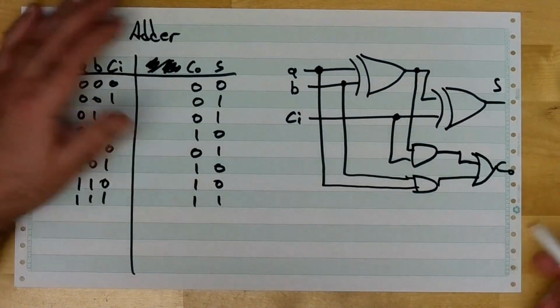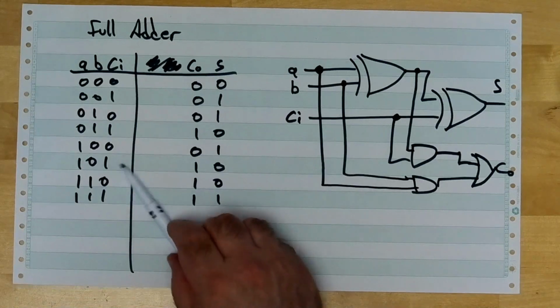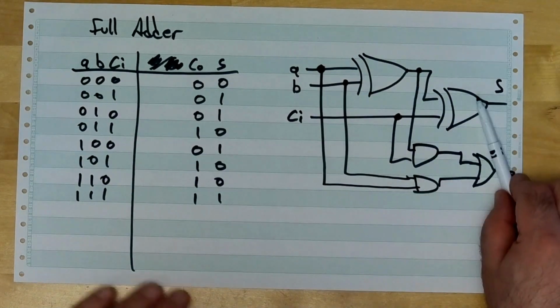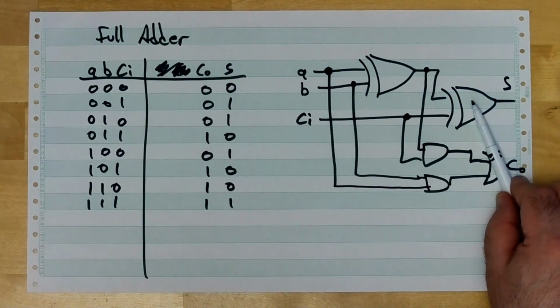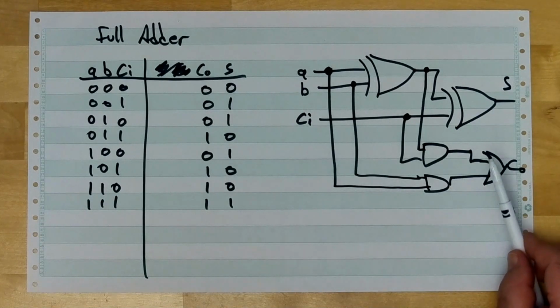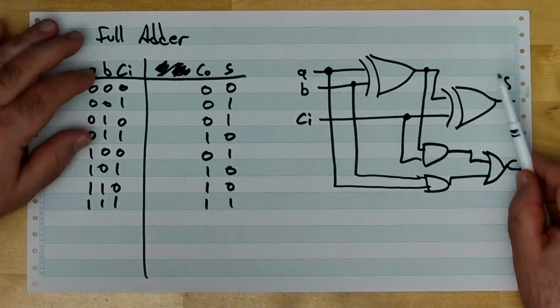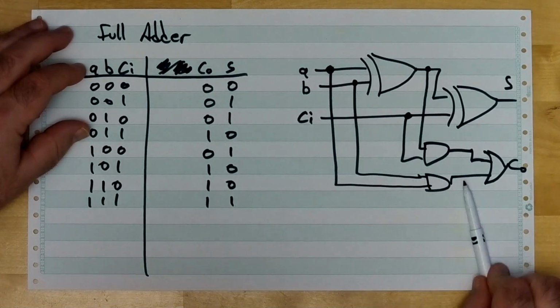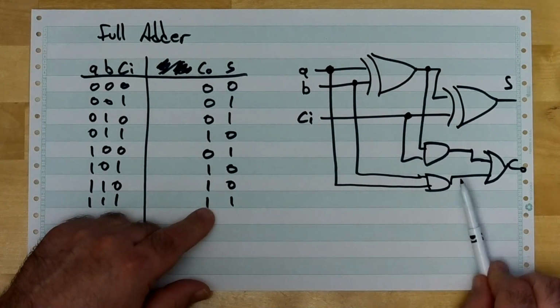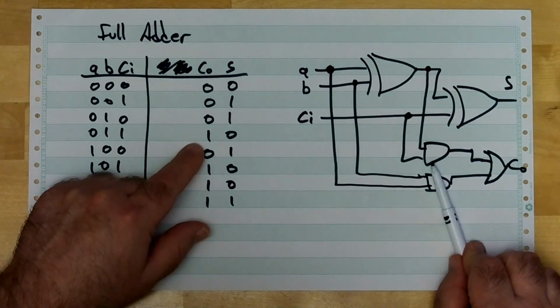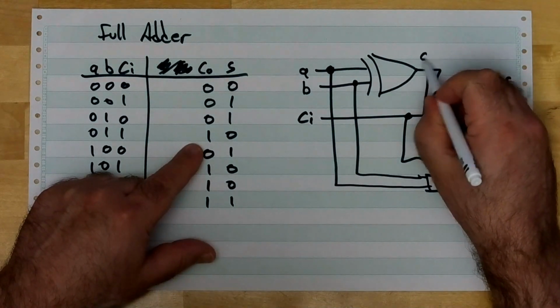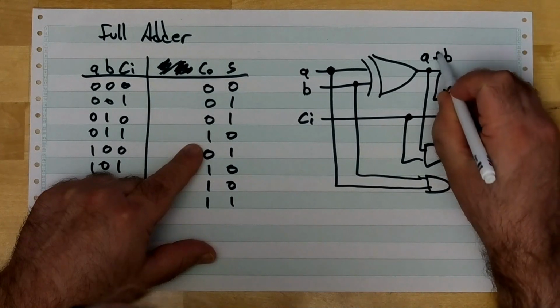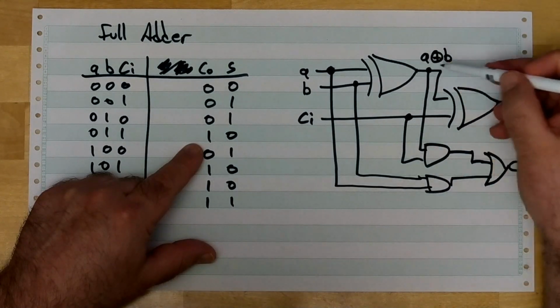All right. Now let's look at this circuit again. I already discussed the sum and how you can just cascade these XORs together and get that to come out. You can do the reduction in Boolean algebra, and you can find that this is one of the possible ways to implement this thing, okay? Especially for the carry. Look what's happening with the carry here. What is this? This is A XORed with B, right? That's what's coming out of that gate.